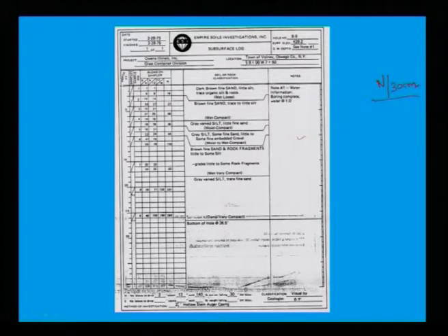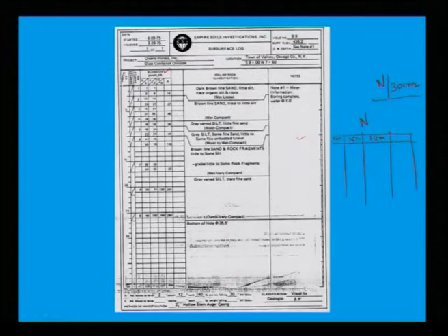What they will do, this is your N, simply they write N, this is your sample blow N. So, what they generally put is 15 centimeter, 15 centimeter, 15 centimeter. Then they leave it to the design engineer, they decide. Generally we discard the penetration value for the first 15 centimeter. Despite we discard, please provide it. So, it will be a very clear picture.